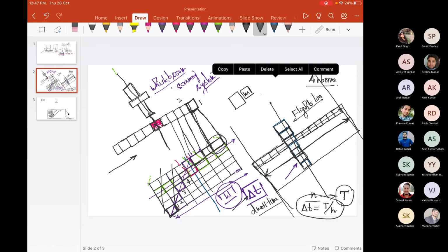Similarly, in the adjacent case, there may be some overlap. Okay, but what we consider is that this CCD is uniquely sensing the adjacent ground resolution cell, but practically, it is not possible. Some part of energy from the adjacent GRC also falls within the CCD2 due to spread of energy in the atmosphere.